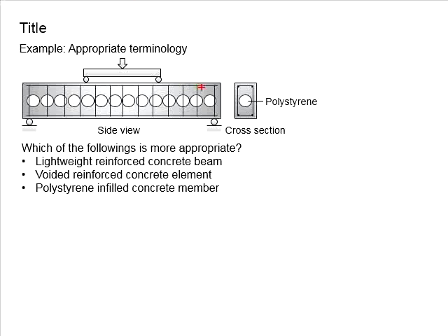It is a reinforced concrete beam. An experimental test was conducted. The beam was tested under a 4-point load test setup. This kind of testing is normally considered a simply supported beam.